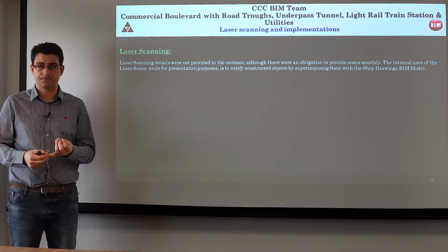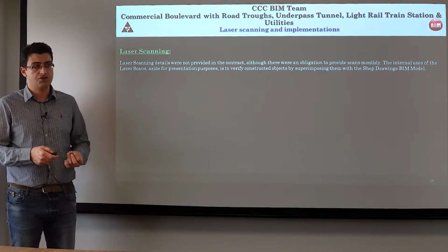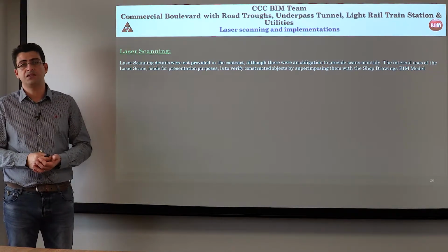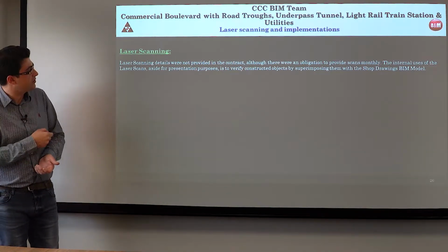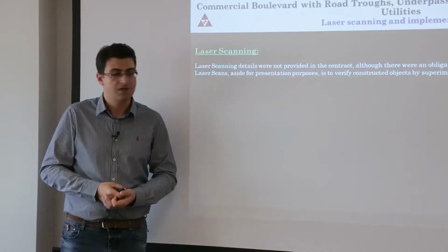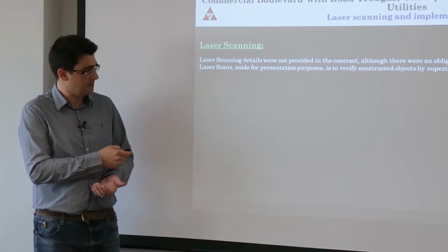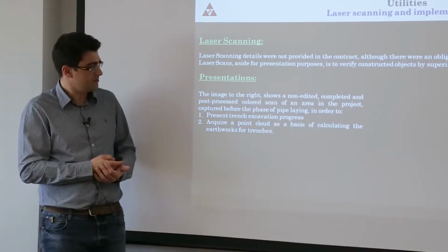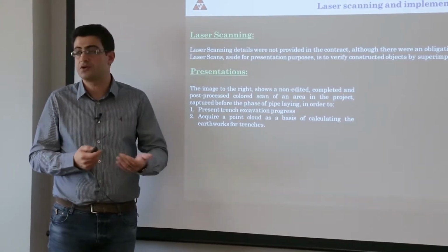So we have the geometrical consistency that is being verified by a technology utilized for the last 10 to 15 years, which is laser scanning, and the data, as we said before, with the checks from C3D. Coming to the laser scanning processes, you can see that we didn't have a lot of details because it's a new process on our project, but there was a need for monthly deliverables. So we had some monthly deliverables of point clouds for presentations, for reasons to get the excavation progress, for example, or the concrete progress.